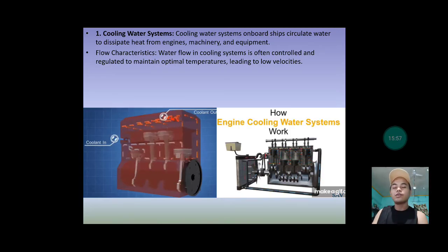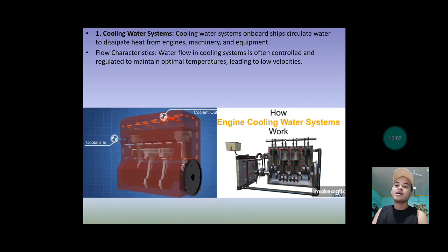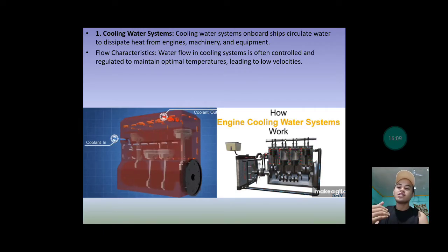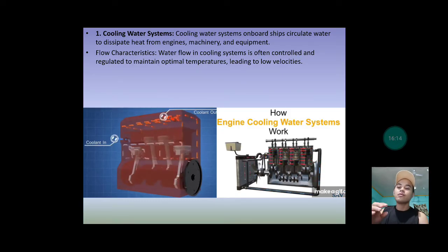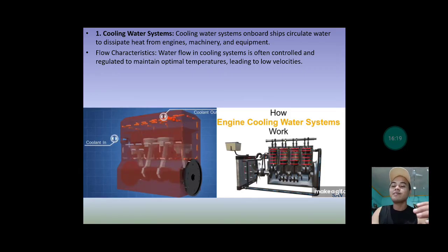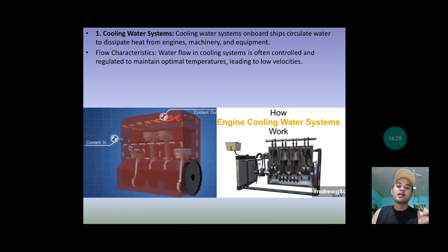If your cooling water moves fast through the system, it will barely absorb any heat from the engines. But if you lower the velocity of your cooling water, the longer it stays in the system or in the engine, the better it will be at absorbing heat from the engine, thereby cooling down the engine and preventing overheating.